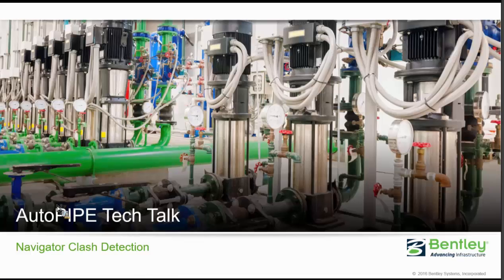Next, the engineer or the CAD designer will take that exported DGN model and will open it in Bentley Navigator to run a clash detection. Piping clashes with other pipes, structures, equipment, and/or HVAC are not uncommon, and they can be very costly to redesign. In some worst-case scenarios, plants actually have to be shut down for failure investigation and repairs, so of course we'd like to avoid that at all costs.